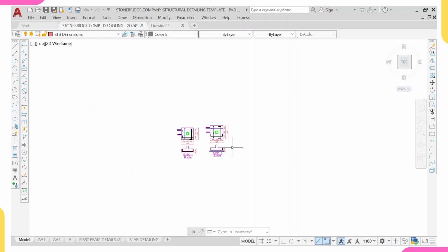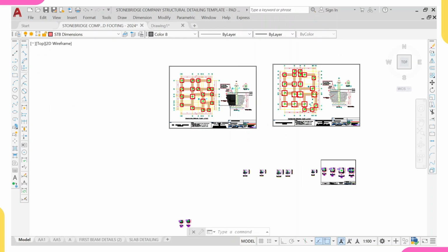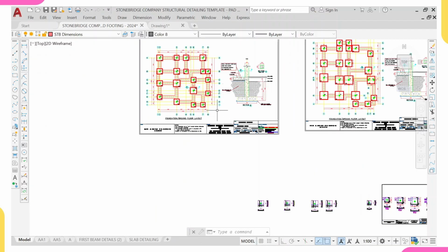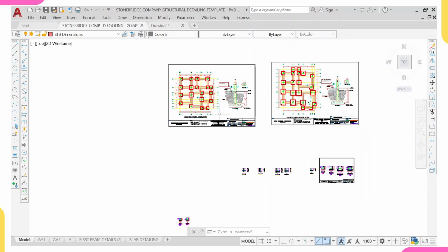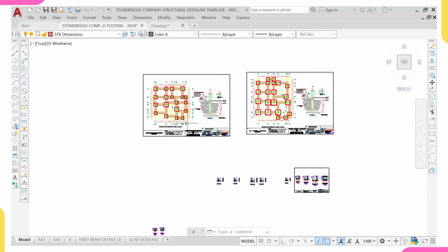Don't forget, this building that you are seeing, we started from the architectural planning. Then from the architectural planning, we moved to the structural framing, and we were able to disclose all the governing principles in structural framing, which is that your slab area should not be more than 30 square meters. Your column should be limited to a spacing of 6 meters. And also in your beam, try not to have much point load acting on your beam. These are most of the governing principles we were able to disclose during our structural framing. Then we did the modeling in ProtaStructure. We did the analysis, and also we did the design in ProtaStructure.